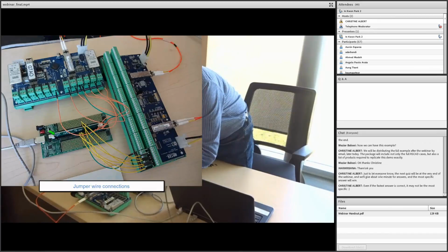I intentionally used different jumper wire colors. The orange wires represent the analog interface between the GT I/O card and this control board. And the yellow wires represent the digital interface between this control board and the RTDS. Of course, the simulation values would be sent from the GT I/O card to the controller. If you look at the controller baseboard, there are 8 pins of analog input on this side, and the connections are made between the GT I/O card channels and those pins.